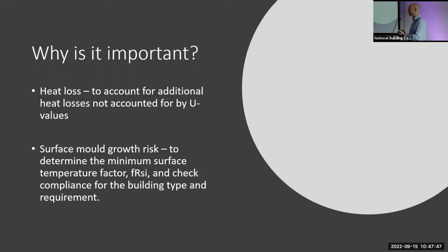And especially when it comes to multi-unit residential schemes, where you've got a huge amount of repetition of detailing, the economy of scale in carrying out thermal modeling on those makes absolute sense. The savings you will make on carrying out thermal modeling to use calculated versus default values is just an absolute multiple. It's a no-brainer.